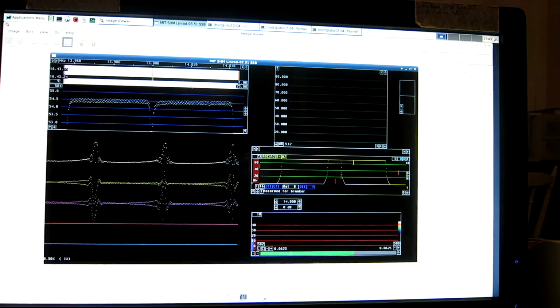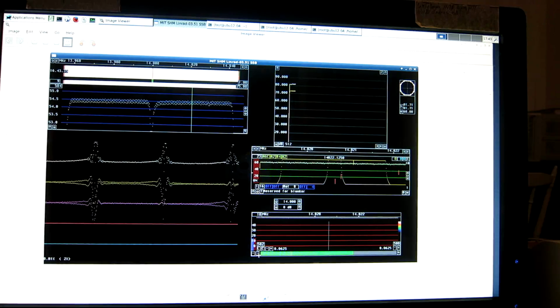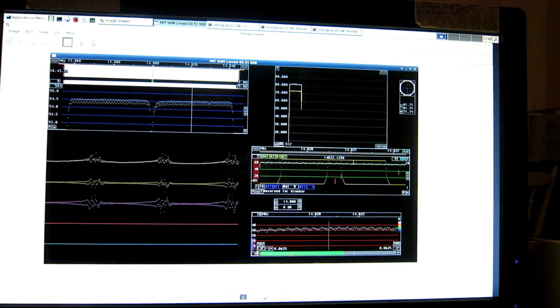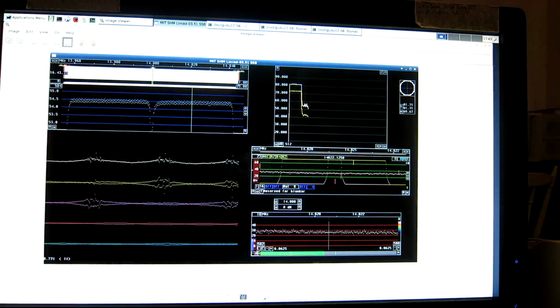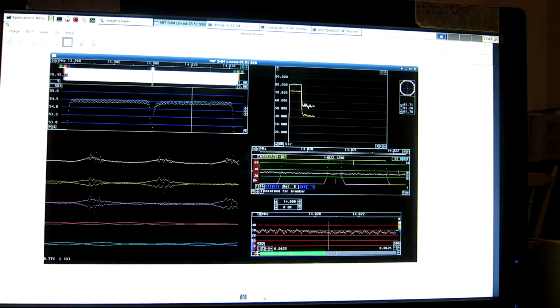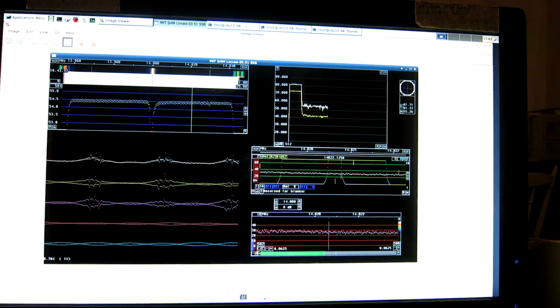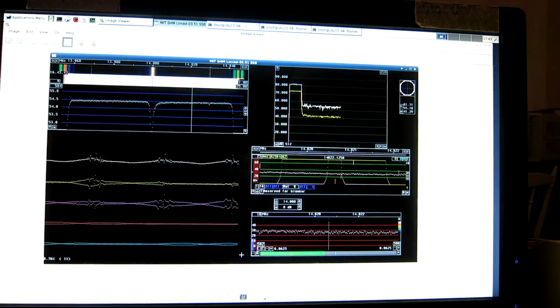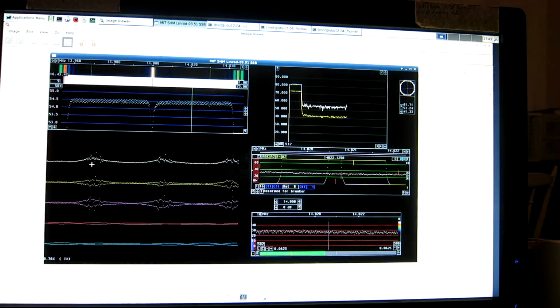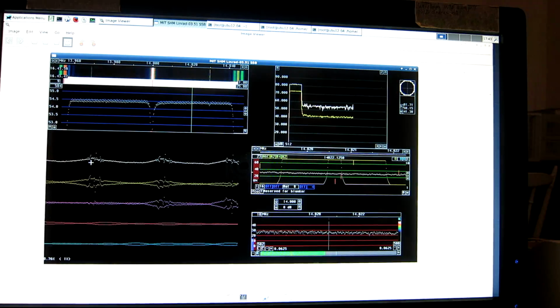Select the frequency and enable the smart blanker. And now it goes down from 72 to 40. That is 32 dB about. Not too bad. And you can see the pulses are gone